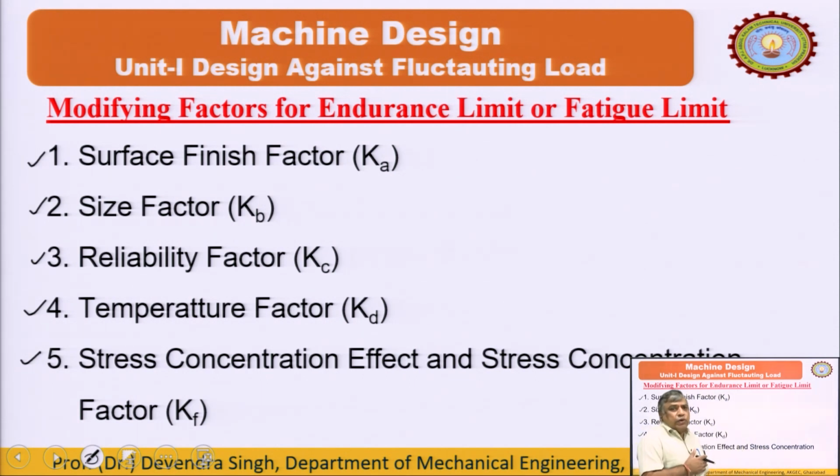So, whatever reliability is desired for a particular component, some factors we use to modify the endurance limit in our design. Then the temperature factor, we are aware of the thermal effects on the strength. So, we use this temperature factor to fight against the thermal effects.